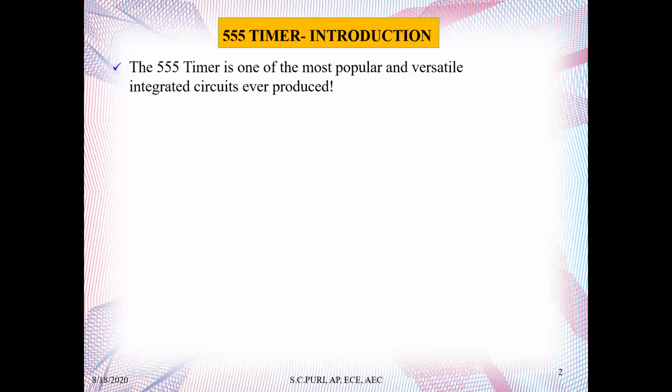This 555 IC is a very cheap, popular, and useful precision timing device, and it can act as either a simple timer to generate single pulses or long time signals, or even a relaxation oscillator producing a string of stabilized waveforms of varying duty cycles. It can range from somewhere around 50 to 100%. This 555 timer chip is an extremely robust and stable 8-pin device and can operate as a very accurate monostable, bistable or astable multivibrator.